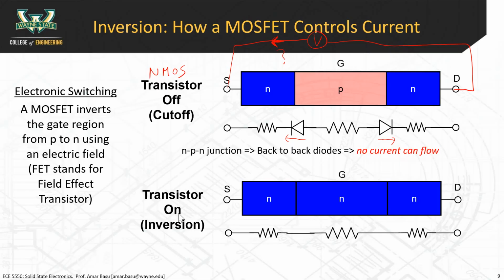So carrier injection requires that you have carriers coming in from another source, and that expends current. That would take up power, and I think that's one of the reasons why it's not done. And then you'd also have to worry about where those carriers are going. Now, doping is a way that we can invert a material, sure, but how long does it take?